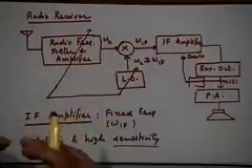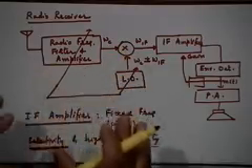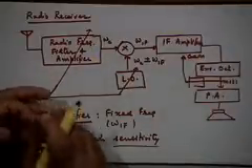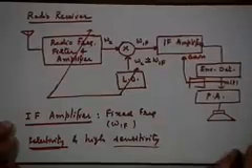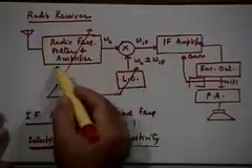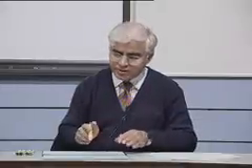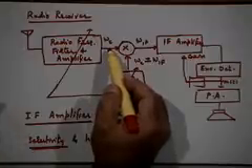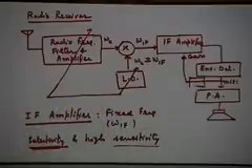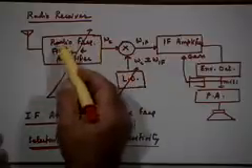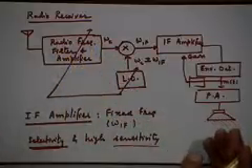So, therefore, the selectivity requirement of the RF filter is still there, but it is a very moderate selectivity requirement. What you are saying is that the two carrier frequencies, which are separated from each other by 2 omega IF, be separated at the RF stage itself, and that is the solution your friend was proposing here, which is the right solution. So, the image frequency will not be a problem if we make sure that your radio frequency filter, the radio frequency amplifier that you have at the input stage, is at least slightly selective to make sure that when it is selecting omega c, it rejects omega c plus 2 omega IF. Typically omega c plus 2 omega IF is well separated from omega c, so that separation should not be a major problem. Realizing an RF filter with that kind of selectivity should not be a major problem.